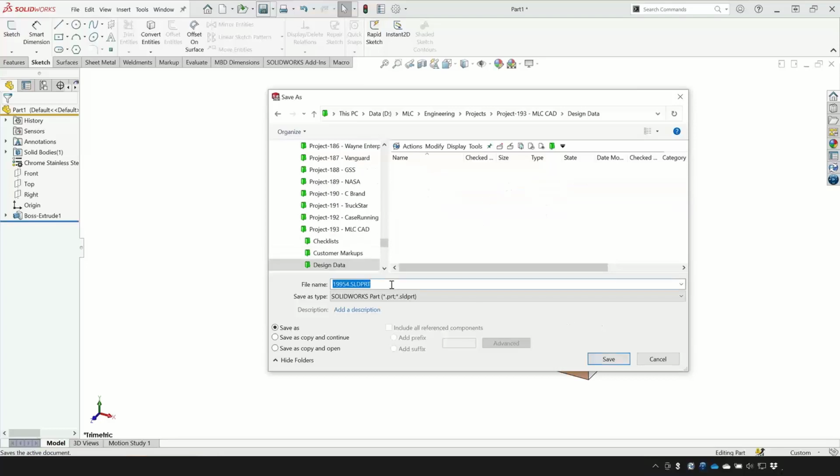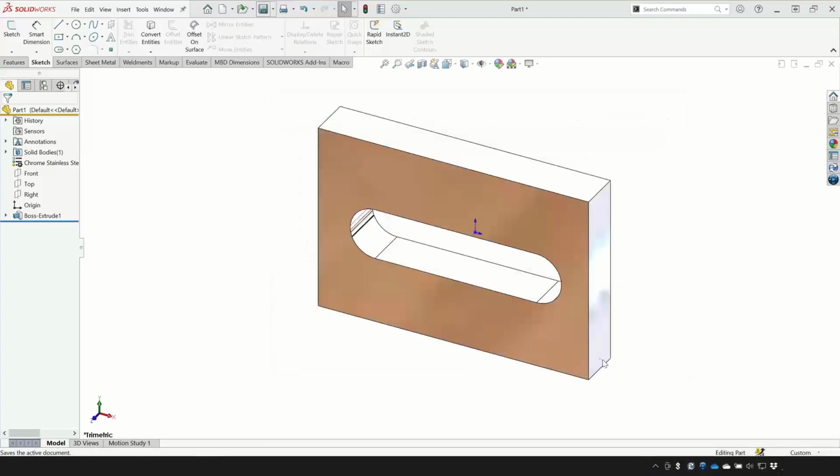Now, you'll notice that the automation that's occurred, that's available in PDM Professional, is it's numbered this for me. My data card has the auto numbering turned on, and it's serializing it. So if I create this one, it's 954. The next one that I create in the Vault will be 955, and so forth. You'll see that when I save this on the data card.